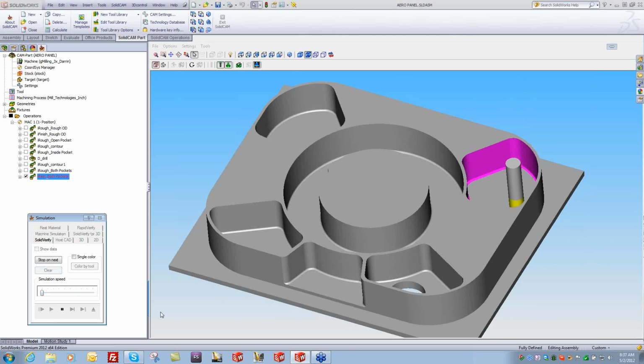That's taken off 5 thousandths off the wall because rest automatically takes a little extra off the wall. We dropped it down to 5. That's why you see the first pass, then it comes back in and it whittles out those corners. Now you'd still need to do a finishing toolpath on this as well, or you could take out that 5/1000 that it's leaving when it's doing the rest and just have it go ahead and finish.